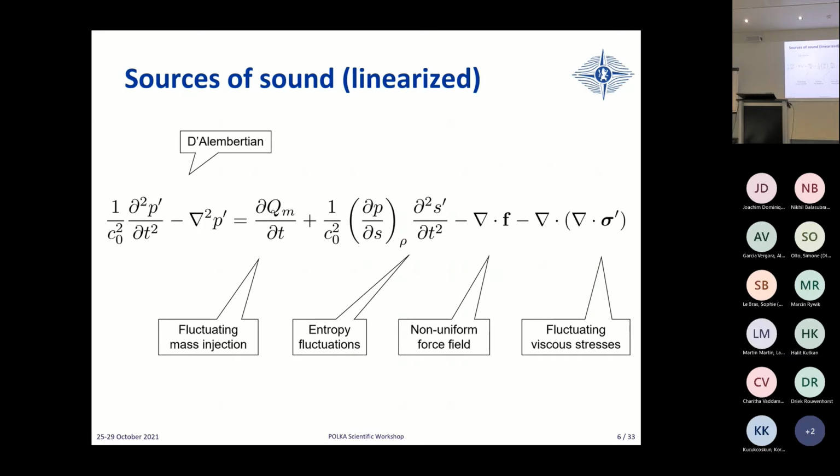That's going to behave like an acoustic dipole, because there is one space derivative, and this one is going to behave like an acoustic quadrupole because you have two space derivatives. If you have a term with three space derivatives, it will be an octupole. And then we find the limit of my vocabulary. I don't know what four space derivatives would give, but that's a case that you will not meet very frequently in practice. Okay, so we have this multipolar decomposition of the equivalent source field.